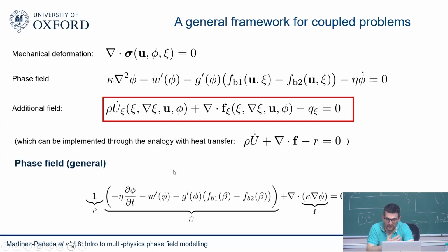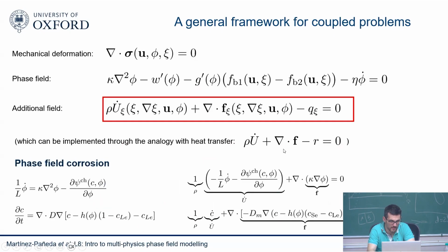And then in the case of a general phase field model, the same thing. So this is valid for microstructural evolution as well. If you wanted to implement microstructural evolution and mechanical load into Abaqus, very simple. With a UMAT HT, you define this as 1, R equals 0. This becomes your F. This becomes your U dot. And so you need to put a line of code in your subroutine. I'll show you in a minute how you do it.